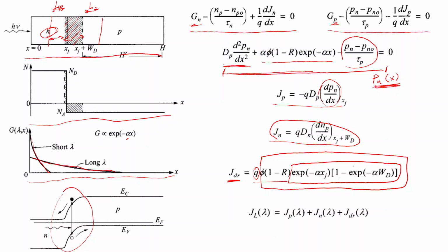So total amount of charge carriers per unit time, per unit area in the depletion region, times Q, gives us drift current, because we assume that all of these photogenerated charge carriers will be collected and contribute to photocurrent, because we have a strong electric field and they don't recombine.